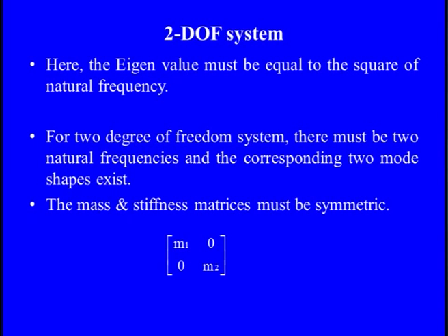One of the significant points in this is that the mass and stiffness matrices must be symmetric. If they are not symmetric, you cannot get the equilibrium feature in any dynamic situation.